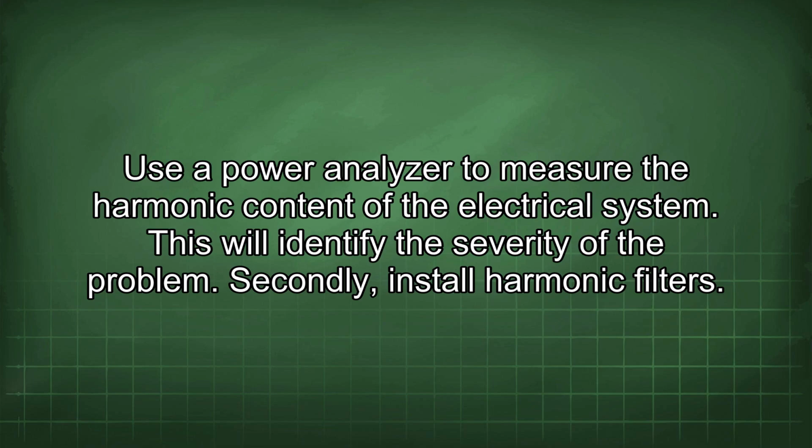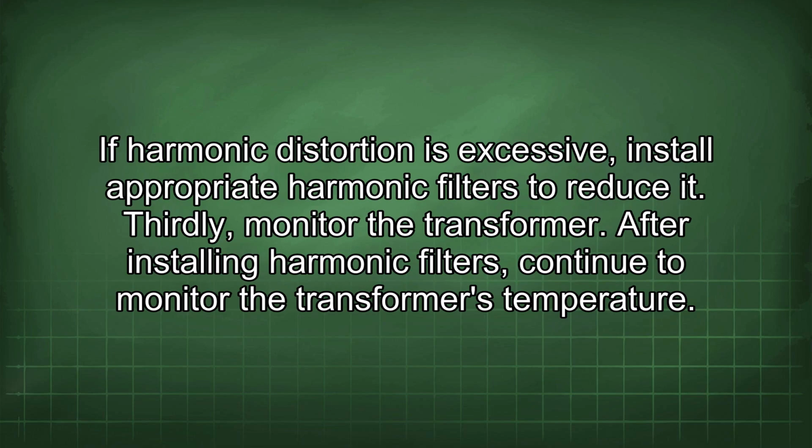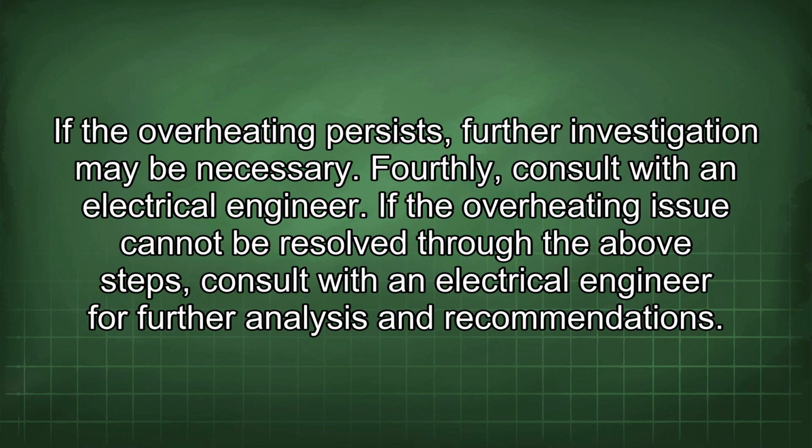Secondly, install harmonic filters. If harmonic distortion is excessive, install appropriate harmonic filters to reduce it. Thirdly, monitor the transformer. After installing harmonic filters, continue to monitor the transformer's temperature. If the overheating persists, further investigation may be necessary. Fourthly, consult with an electrical engineer. If the overheating issue cannot be resolved through the above steps, consult with an electrical engineer for further analysis and